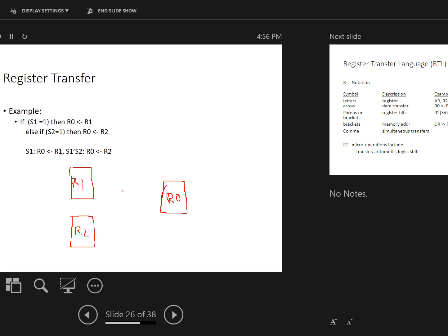the register R0. And we've also seen a good combinational block that we can use for that called a mux. And in this case, if I assume that my registers are 4-bit values, I'm actually going to have four 2-to-1 muxes, or one, we sometimes call this a quad mux. And in the case of digital components, we're also going to want to label the inputs, and especially for our muxes, which lines correspond to 1 and 0.